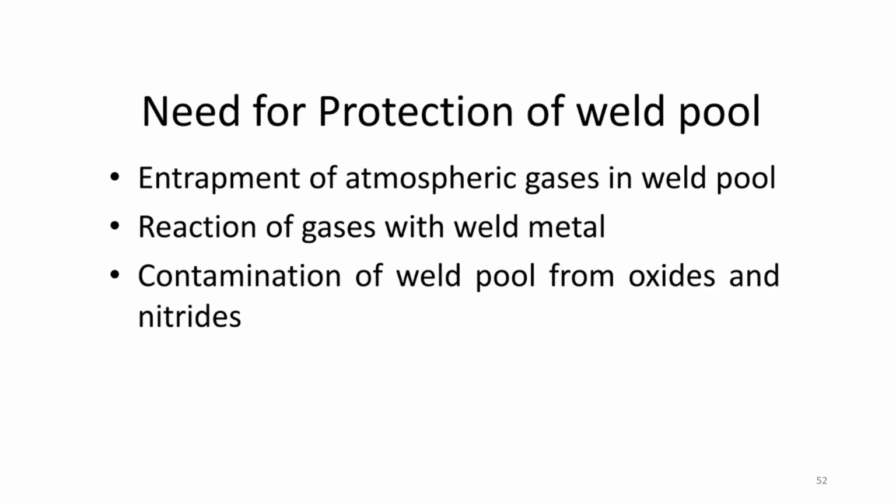So the gas will get dissolved in the molten metal, and then as you solidify it, its solubility reduces. So gases will get entrapped, and there will be formation of some inclusions, or they can make the material more brittle.